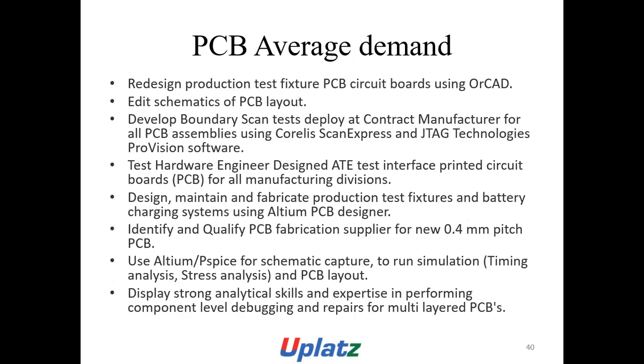Redesign production test switcher PCB circuit using OrCAD, get schematics of PCB layout, develop boundary scan test, deploy at contract manufacturer for all PCB assemblies using Corelis and ScanExpress and data technologies provision software. Test hardware, test engineer design, ATE test interface printed circuit board for all manufacturing divisions, design, maintain, and fabricate production